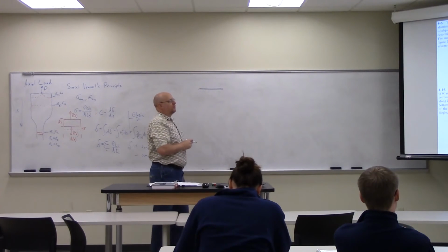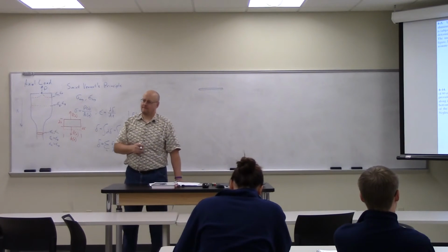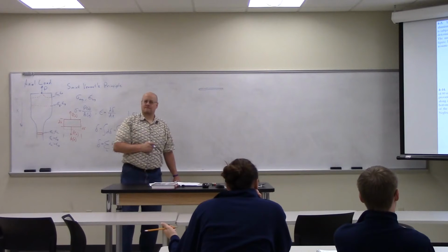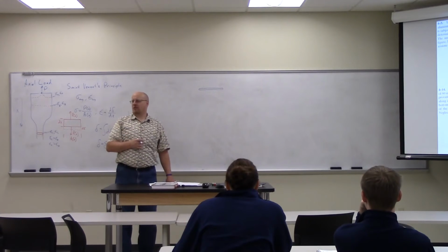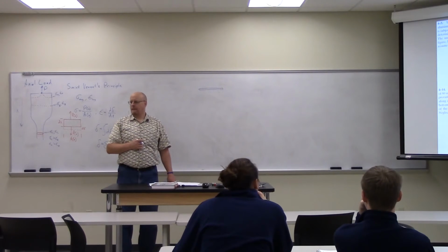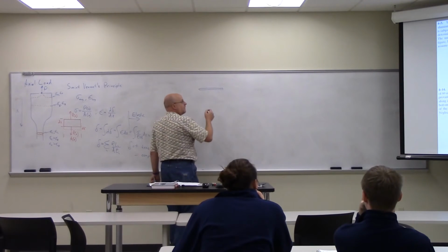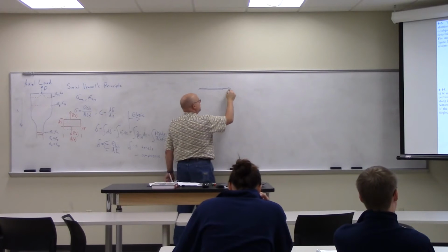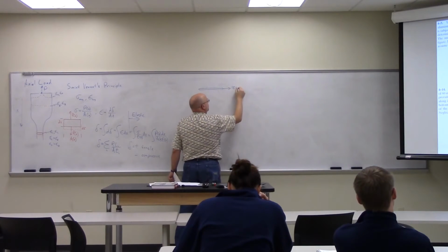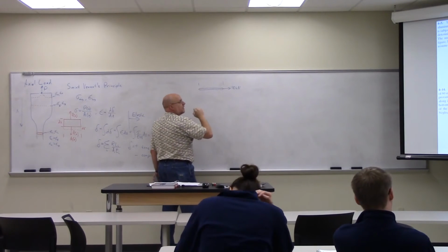So where do you want me to start? Just to the left of B or just to the right of B? I would start just to the right of B. You don't want to put the 6 kilonewton force into a free body diagram? Right. So I've got 18 kilonewtons pulling out here, and a total dimension of this thing of 2 meters.